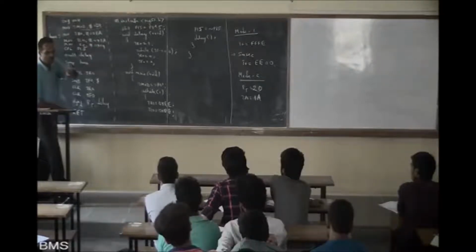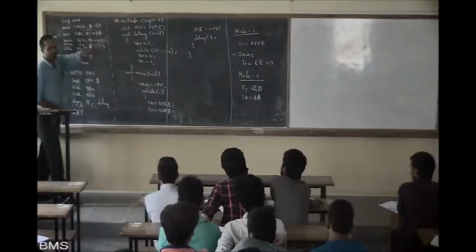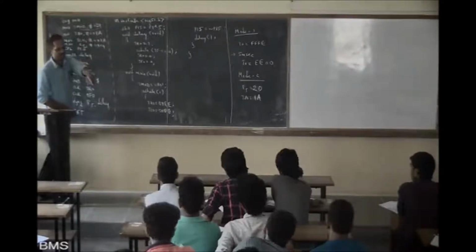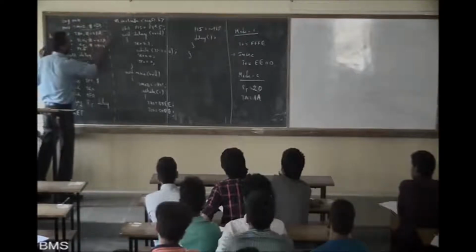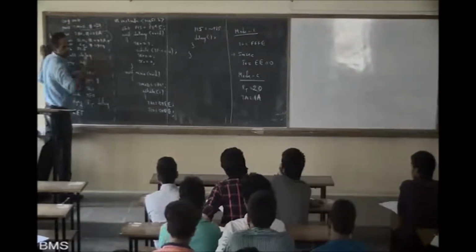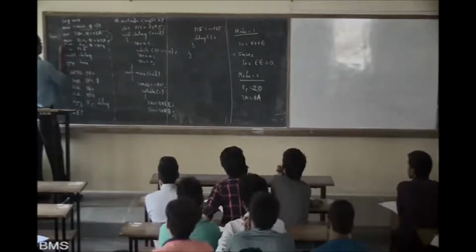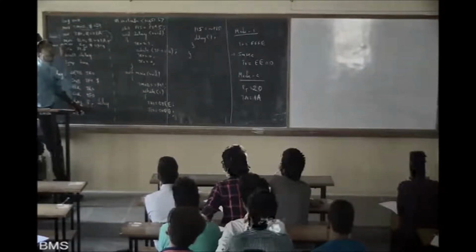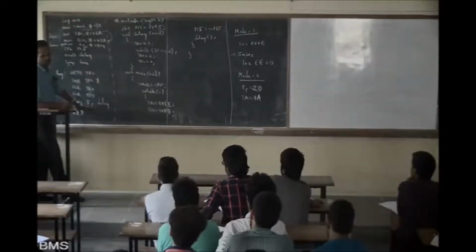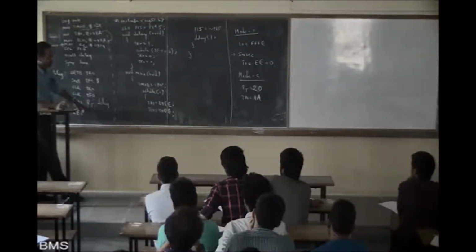As it goes from 1A to FF and rolls over to 00, TH0 will give a value according to the mode 2 diagram that we have discussed. The TH0 value will be loaded into TL0 and then it starts from there. So here it has to be pointing to R5. R5 has become 0 here. We have decremented with DJNZ until it became 0.